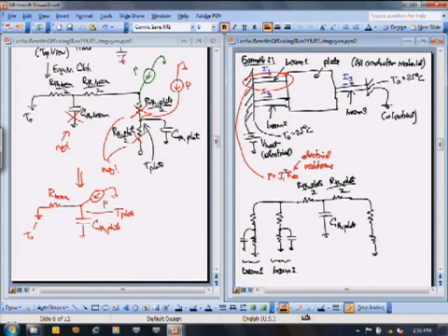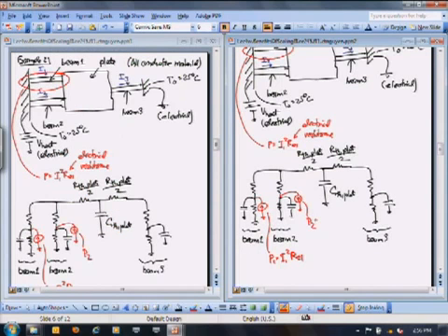And now, I've just identified that there's a power source associated with beam 1. And so I have to put that power source into this thing. So this power source is coming right here, and that's the power that I'll call P1. Let's put this on that side. That's equal to the current I1 squared times RE1. I've got another power that's going into beam 2. That's P2, I2 squared times RE2. I do have another power source going into my plate. And I've got another power source going into beam 3 that I'll call P3, I3 squared times RE3. So I've got all these power sources now going into this.